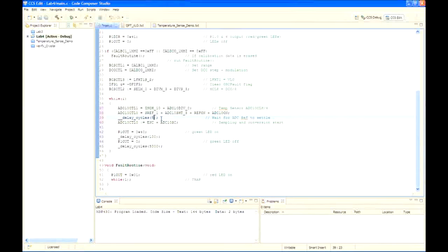The next line, the ADC10 CTL0, enables the conversion and starts the process from software. According to the user's guide, we should allow 13 ADC10 clock cycles before we read the conversion result. 13 cycles of the 5 megahertz ADC10 clock is 2.6 microseconds. Even a single cycle of the DCO over 8 would be longer than that. So we'll leave the LED on and use the delay so that we can see this with our eyes. So leave the next two lines alone.